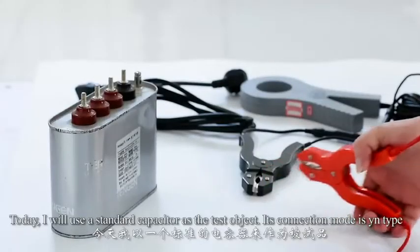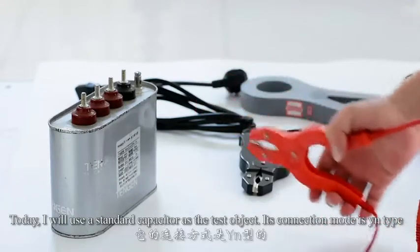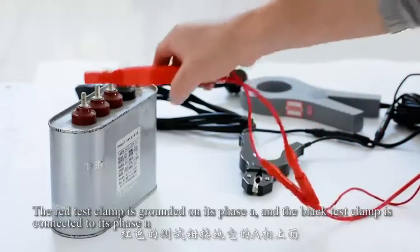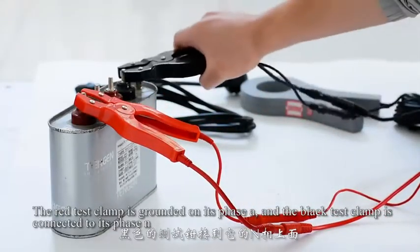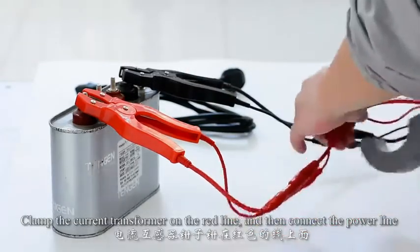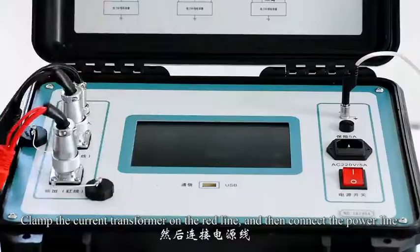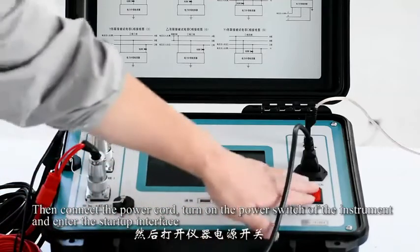Today, I will use the standard capacitor as the tested object. Its connection mode is 1N type. The red test clamp is connected to its phase A, and the black test clamp is connected to its phase N. Clamp the current transformer on the red line, and then connect the power cord.